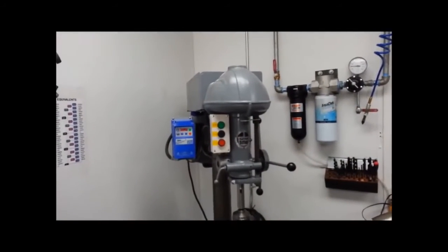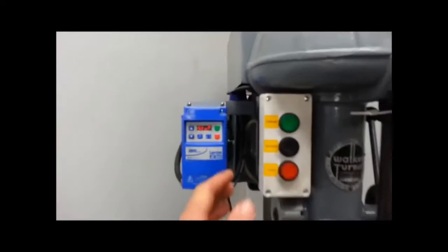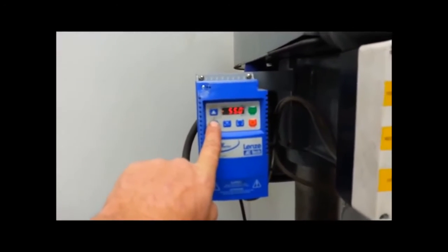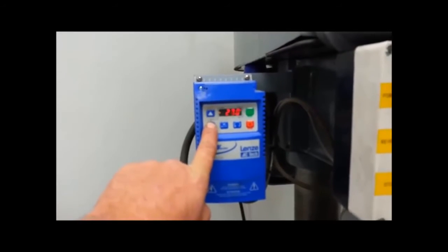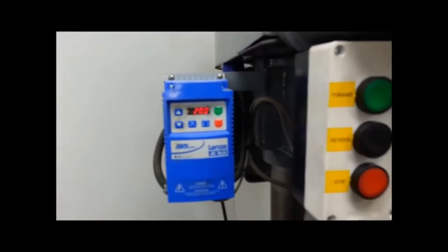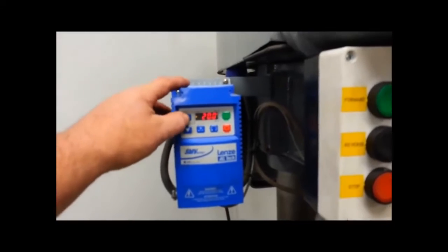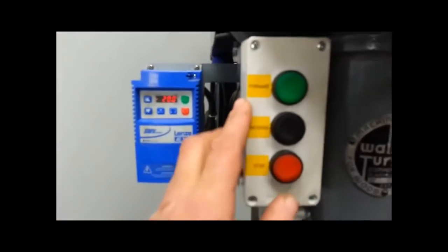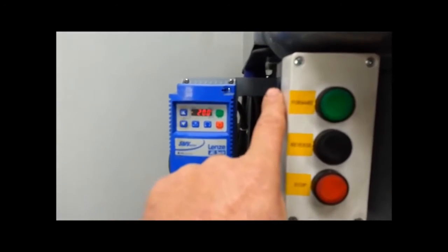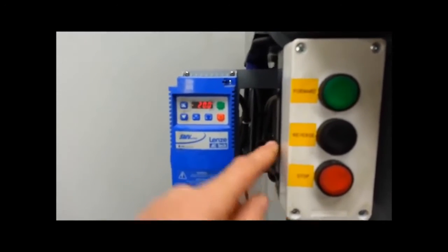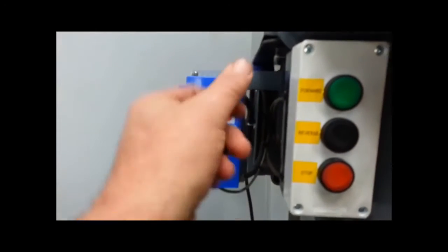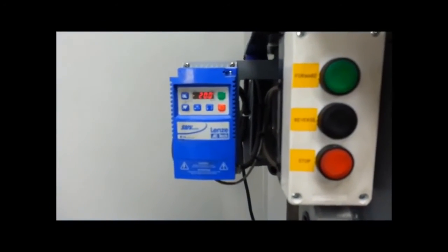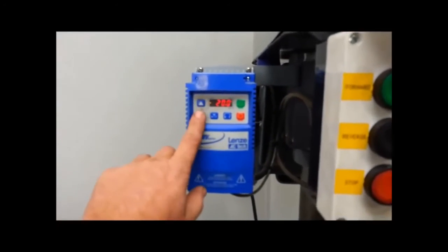Speed reference on that one, I use the push buttons right on the VFD because it's right there. So I just bring my frequency down right there. I could very easily program this to run off of, I could have 2 more push buttons. Push one to ramp up, push another one to ramp down. I could have a speed pot here where I could just turn it one way or the other. Or just go right off directly off the keypad.